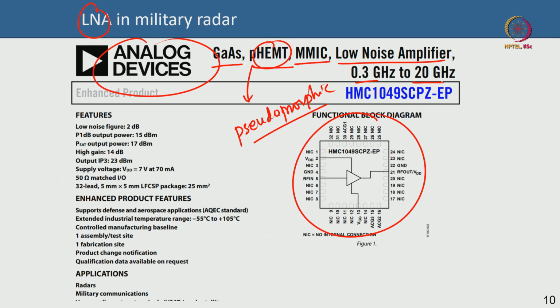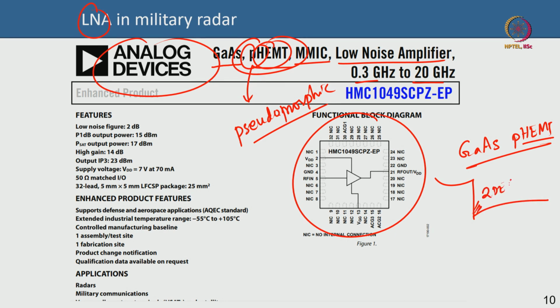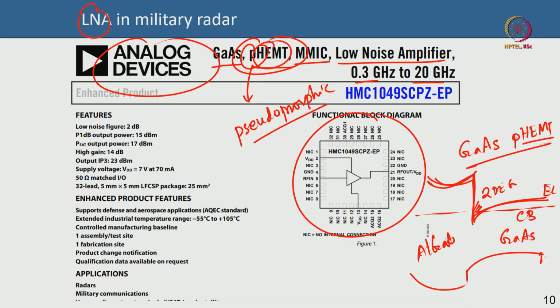Can you see that? In this course we will talk about gallium arsenide pseudomorphic HEMT among other devices. So what is a HEMT? A HEMT is a device where you have a barrier layer and then you have a channel. There is something called a two-dimensional electron gas. What did I draw? I am drawing the conduction band profile, and this is the valence band profile. So this is gallium arsenide, this is say aluminum gallium arsenide, this is an alloy, a larger band gap alloy, and this is the Fermi level, this is the conduction band, this is the valence band.